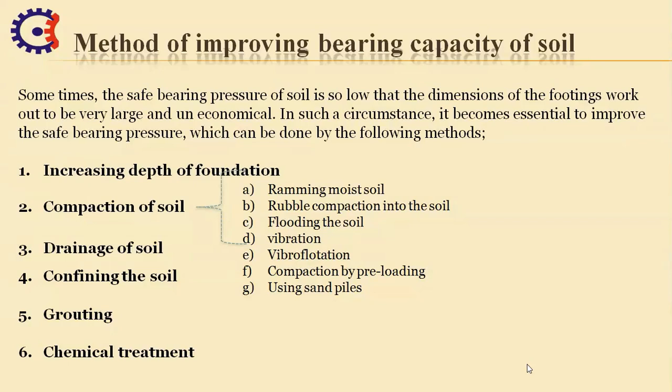Then the next is confining the soil, and the next is drainage of soil. In this method, the soil is enclosed with the help of sheet piles. This confined soil is further compacted to get more strength. This method is applicable when there is a shallow foundation, and many more. Next is the grouting material.